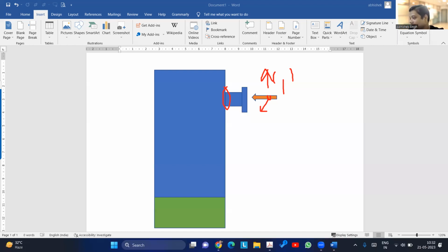In WRC at the junction, at the shell to nozzle junction. See, the WRC calculation has been performed. So definitely the nozzle load will be considered at some point, right? And it cannot be the nozzle face because it does not talk about the length part of it.